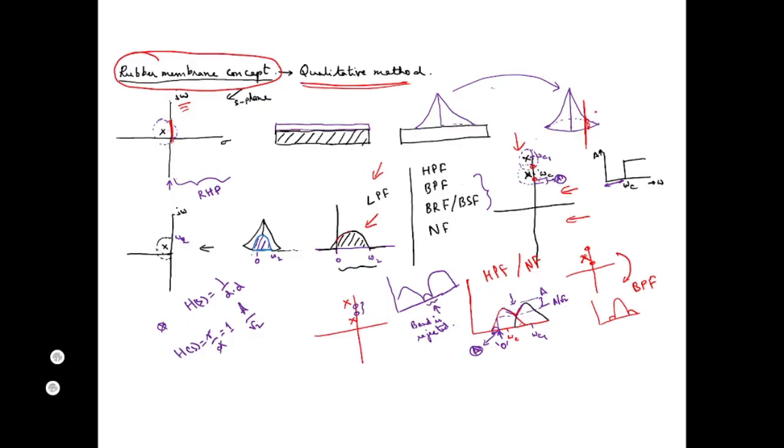Suppose this is the frequency axis, as I told you, and I am moving this towards this thing. What is happening? This higher portion will come over here, they will shift. So the gain at that particular frequency will increase, right? And if you take this pole and push it away from the axis, what will happen? Gain is decreasing. Okay. So placing a pole nearer to the frequency axis increases the gain of the filter.